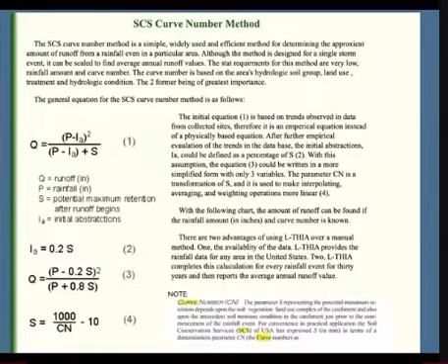Note: curve number, the parameter S representing the potential maximum retention depends upon the soil, vegetation, land use complex of the catchment and also upon the antecedent soil moisture condition in the catchment just prior to the storm.